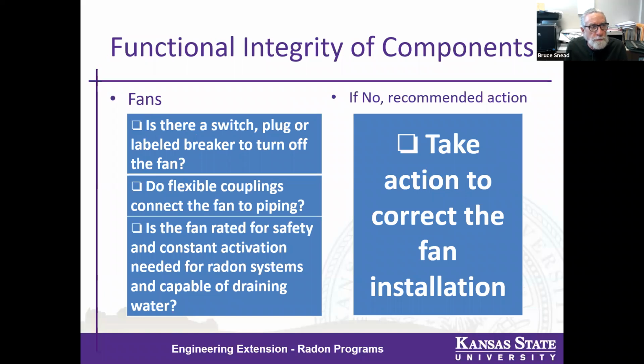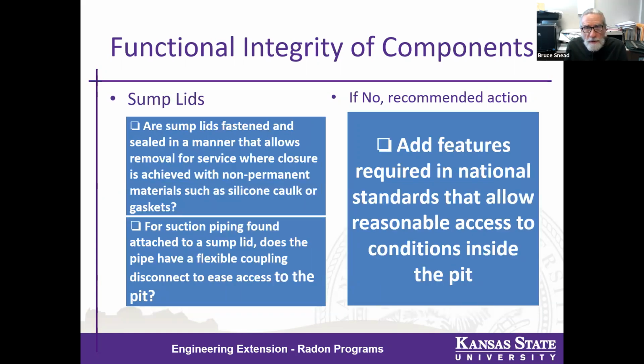Fans. Is there a switch, plug, or breaker to turn off the fan within visible area of the fan? And are there flexible couplings connecting the fan to the pipe? And is the fan properly rated for radon system use and capable of processing water? Sump lids, are they fastened and sealed in a manner that allows removal for service? Are there flexible couplings that allow access for service?